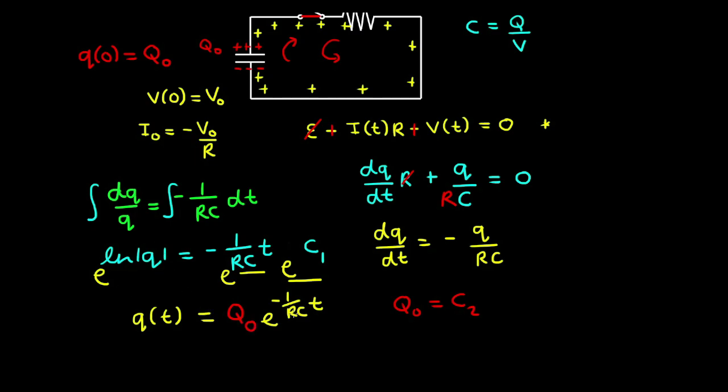And again, we take this quantity, RC, as time tau. So therefore we can write this as e to the minus t on tau. And the significance of the time constant will become apparent when we analyze this solution.